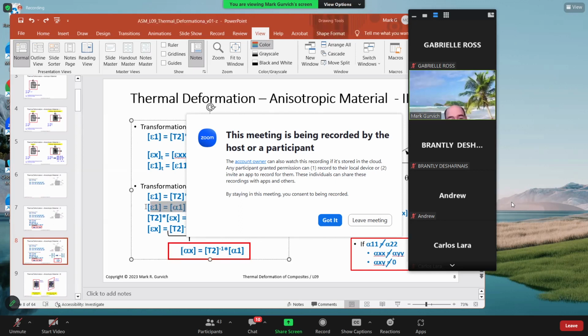Half strains are correlated with moisture, or absorption of moisture. So instead of delta T it will be a factor defined by moisture, and instead of alpha it will be a matrix of proportionality, but the same logic. But because moisture has a much smaller effect than thermal deformation, I removed it from here, but I just want you to know. You will be aware.